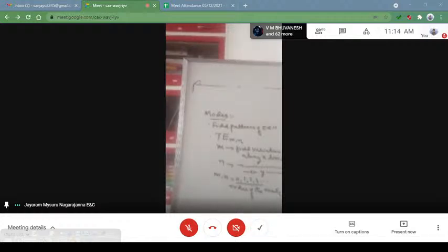This results in a wave that is not propagating in the waveguide, and hence m equals n equals 0 is not possible in a waveguide. Other combinations like m equals 1, n equals 0, or m equals 0, n equals 1 are possible because at least a few components will be non-zero. So that can be written in this form.